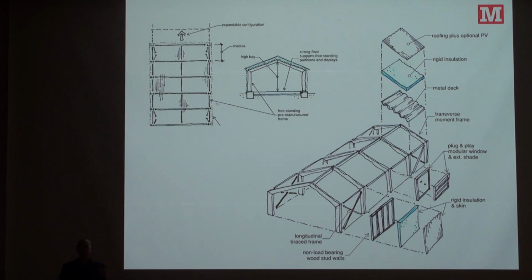And so in this, we purposely made this frame robust, meaning it's not optimized. There is actually a tension between optimization and robustness, and with robustness, there's flexibility. So here, this design called for flexibility. And so we're overbuilding purposely, because we don't know what's coming. So that's an important decision.